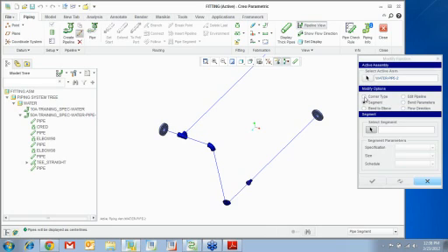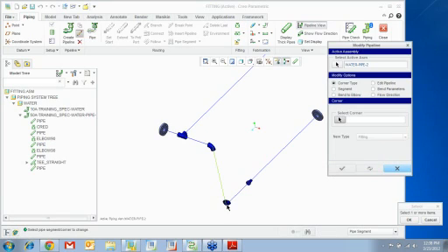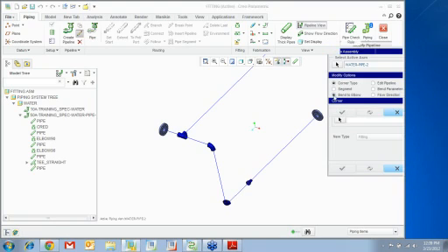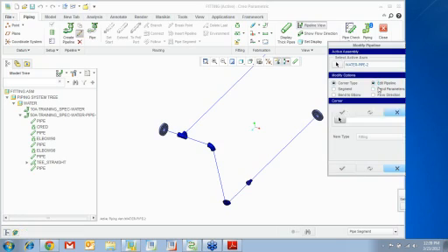You can change the segment, you can change the corner type. So you pick the corner right here, say okay. See, it's defaulting to fitting because that's what my config options are set up to do, but I can use another example and show you the exact same thing, where you can change a bend to an elbow, or an elbow to a bend. You can do those things with the pipeline.